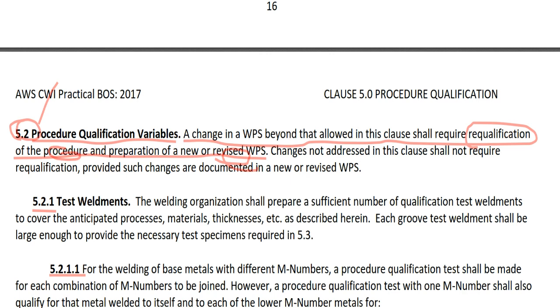Procedure here means PQR, procedure qualification record. So it takes time and it takes cost. Changes not addressed in this clause shall not require requalification, provided such changes are documented in a new or revised WPS.